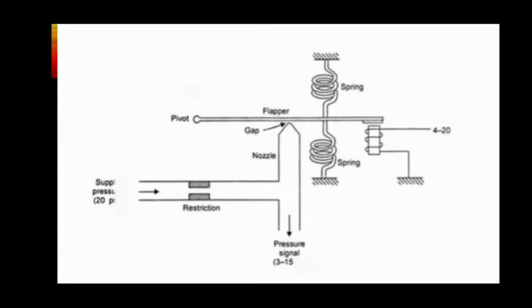The greatest advantage of electro-pneumatics is the integration of various types of proximity sensors, electrical, and PLC for very effective control. As the signal speed with an electrical signal can be much higher, cycle time can be reduced and the signal can be conveyed over long distances.